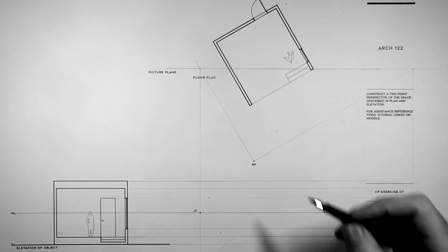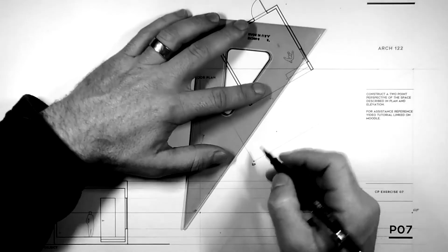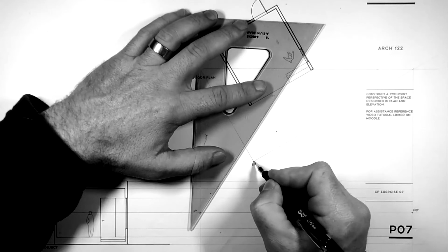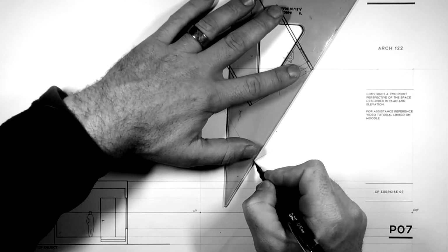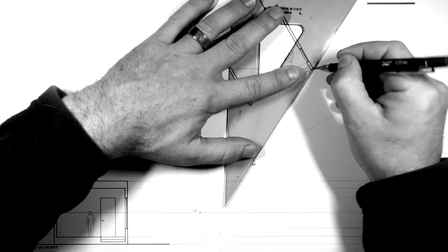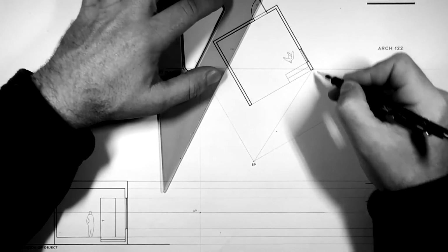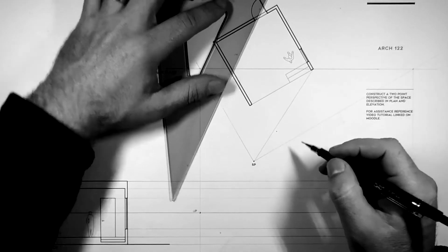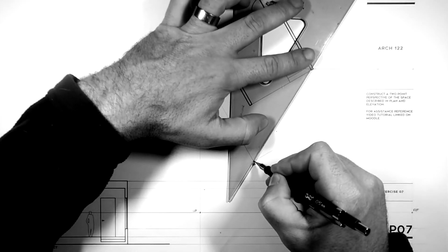Okay, to find the verticals, it's just like the one-point construction perspective. Those angles and those lines can be defined by drawing a line through the station point to the piece of geometry in the floor plan, and wherever that crosses the picture plane, this corner that I've done first, the outside edge of that wall, happens to be on the picture plane. But we also want to define the interior corner of that wall.